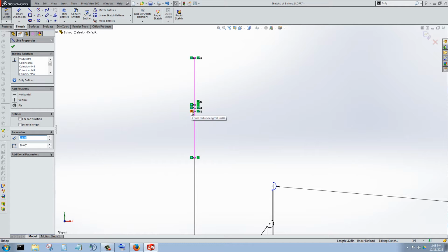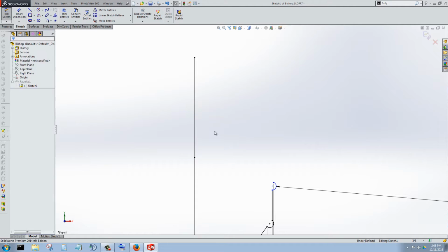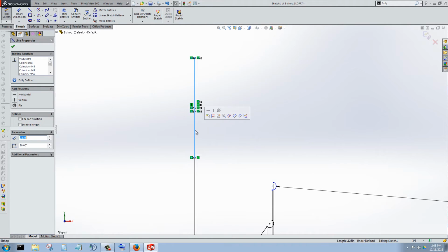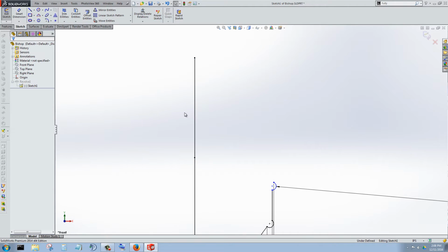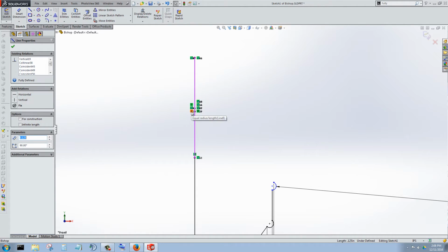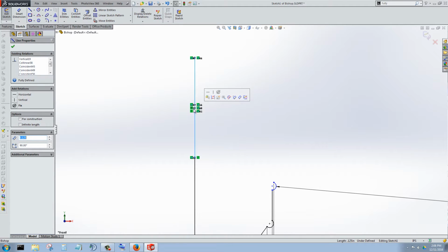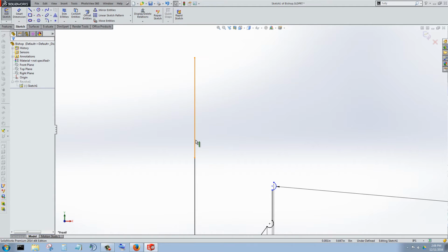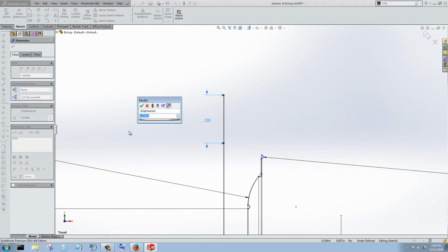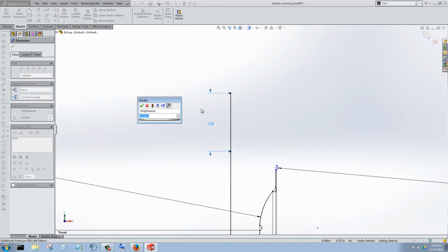Equal radius or length of line 8. Well, what's the name of this line? Well, what if I got rid of line 8 equal radius length? Okay, well, let's delete that reference, delete that other reference, and now let's see if we can change the length of this. Perfect, I can. And I'm going to add some height to the bishop, taller than the rook and the pawn.